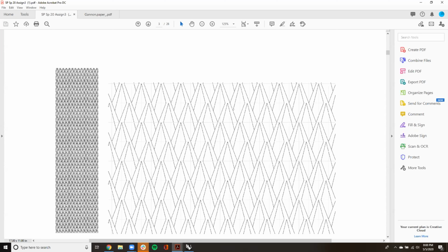What I'd suggest, and this is for everyone, is a concept regarding panelization. You had interactivity of design points between panels. I think you ended up with irrational numbers in a certain sense, something indeterminate where you couldn't actually get a point. Many people have limited or bounded their pattern to the outline of the actual panel, whereas in yours, many of the points that determine something in this panel are over in the next panel. I think that spread of the design across the panels is what is really beautiful about this, but it also makes it a really hard thing to script.